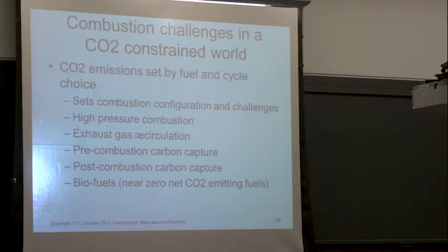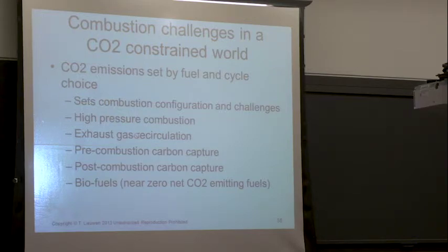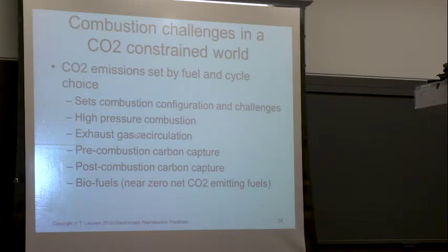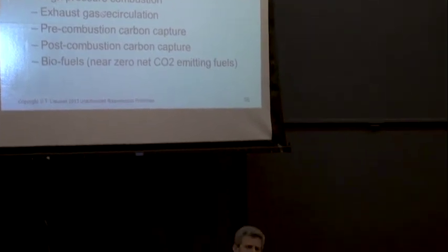And this is interesting because CO2 and water, when you recirculate those back, those are not chemically inert. They're not like nitrogen, which is basically an inert. CO2 is very chemically active. In fact, at Princeton, Yiguang Zhu, a professor here, he's done a lot of work on how you can start to get interesting radiative interactions between products and reactants. So air is pretty much translucent to radiation at combustion pressures, whereas CO2 is not. And so what can happen is the hot combustion products can radiate back. And so you can actually have heat transfer by radiation, not just by conduction, back to your reactants. So that's an interesting problem.